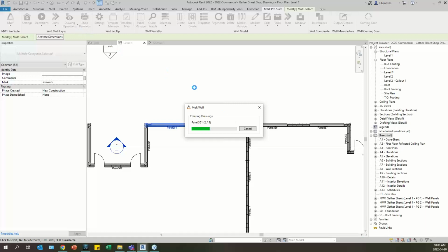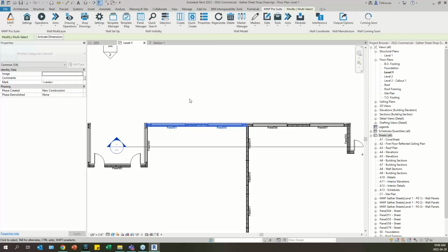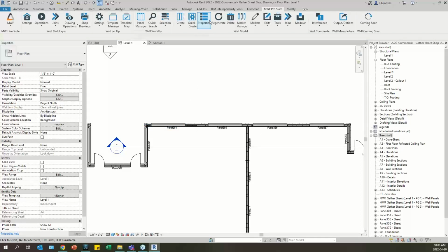And so regarding the refresh command, it's something that you can use when you have minor changes to your panels. If you do have bigger changes, for example, anything that requires regeneration, you would have to run the drawings again, run the shop drawings engine again. The reason is that if you make a major change, let's say in properties, once you get out of properties, it's going to automatically regenerate your panel. When it does that, it loses the updated data that you have in your shop drawings. So you have to rerun again. Just refreshing the drawing will not work in that case.